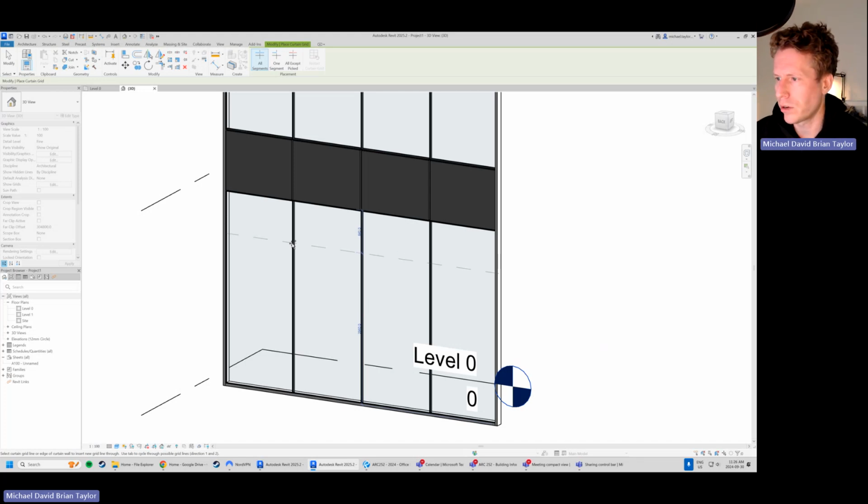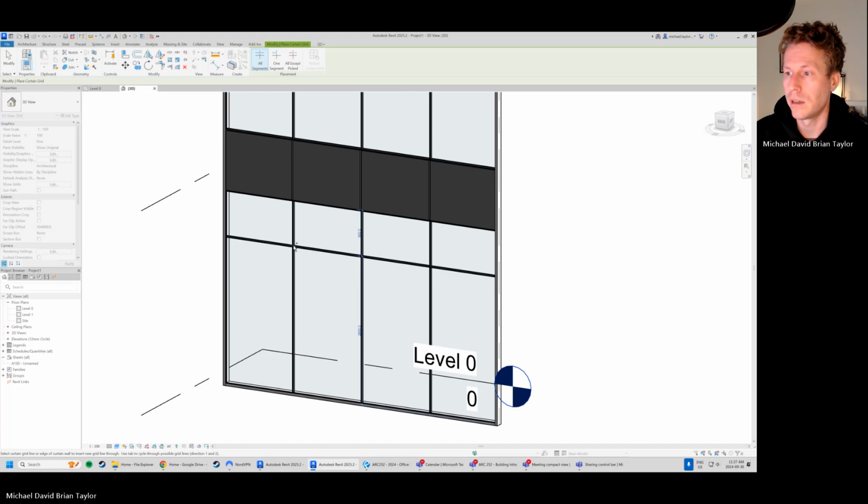So let's say we got a door in here somewhere, call it 2900. And one thing I should mention is that you'll notice that if we want to generate a horizontal grid, we need to be situated on the vertical grid and vice versa, right? So if you're like, why won't it just give me the grid? It's because we need to actually be on another grid line to make that happen. So let's just jump here, 2900, and click once. And we see we've generated a new curtain wall grid. Excellent. And now we've got this additional grid in here.